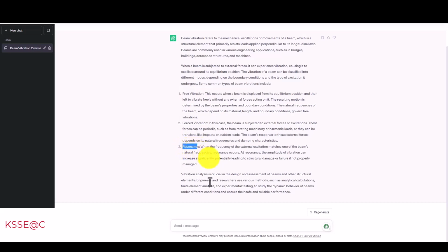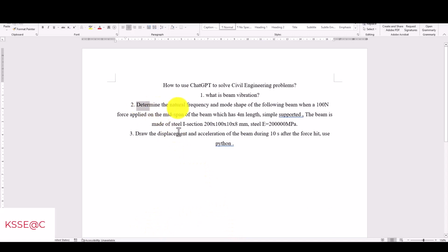And the second is forced vibration and resonance, also a phenomenon where the natural period of the beam and the natural frequency of the force are matched together. Then there will be some resonance, where the displacement goes almost infinite, and then there will be some sort of collapse and damage to the structure. And here's some information.